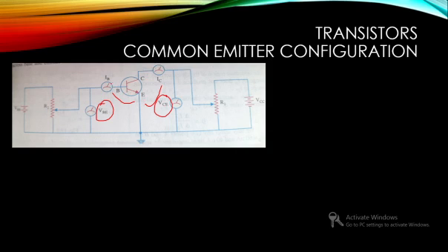Okay, and there are ammeters for measuring the current. And what does this represent? This represents a rheostat, which means we will be changing the rheostat so that we can adjust the voltage drop across the resistance, so that much will be given to the base. We'll be using a battery, and by changing the rheostat we can adjust the supply voltage given to the input.